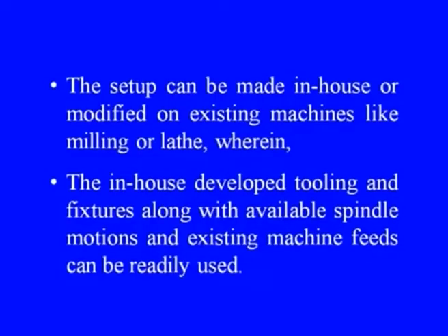The setup can be made in-house or modified on existing machines like milling or lathe. The in-house developed tooling and fixtures can also be used along with available spindle motions, and existing machine feeds can be readily used. That means no very sophisticated arrangements are required to carry out this welding process.